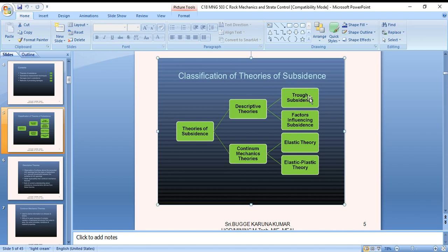Usually, the first indication of subsidence in this type of excavation is a downward flexure, or sag, of the immediate roof, which may be accompanied by floor heave as the areal extent of the excavation is enlarged. The roof sag will increase until either the roof touches the floor or the roof fractures and falls. In essentially all rock types, this phase of the process is time dependent and terminates with the complete closure of the opening.